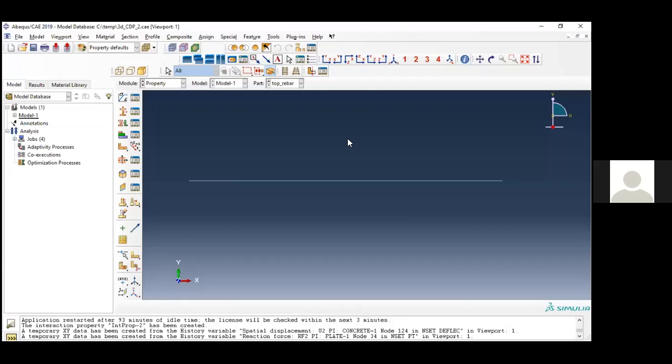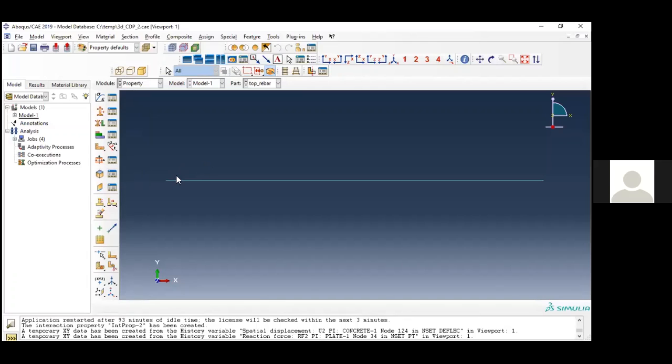So truss is the appropriate element. But some journals show that some researchers found the beam element to be the best option compared to the truss element. They concluded the beam element gives a better result, a value nearest to the experimental result. Maybe if you are considering the cage as a whole, and if you consider an individual bar, it behaves like a truss. But when you consider the whole reinforcement cage, maybe it behaves like a beam. That may be the reason.